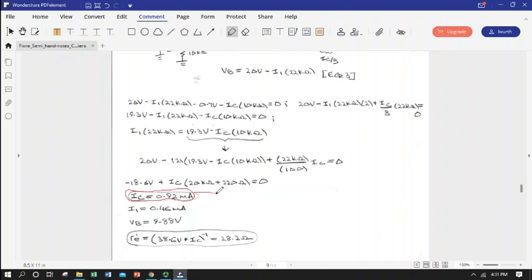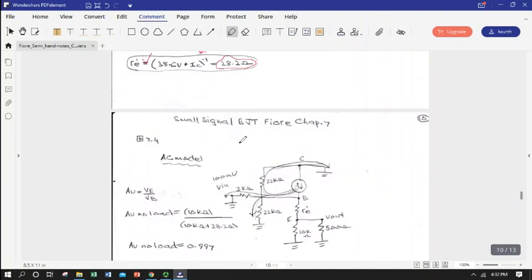But the important thing for us looking at setting up for our AC model is we use this DC collector current, which is our Q point collector current, to define our R little e, our base emitter resistance for our AC model. And 28.2 ohms, very small, very small. That's why we're going to end up getting a unity gain.